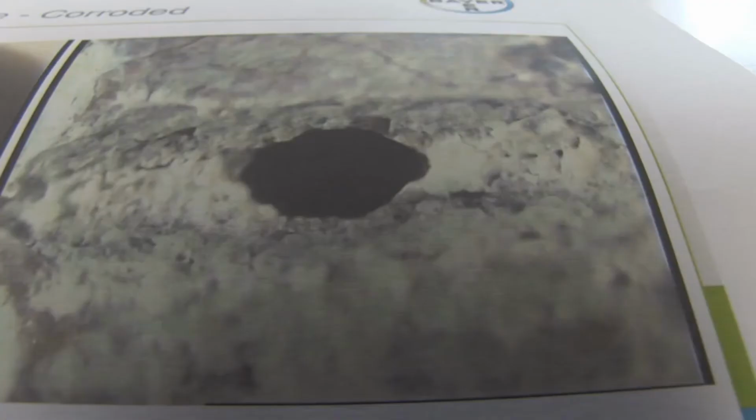I'd suggest brass nozzles, if you're using them quite a lot, have probably got about a 12-month life cycle. So you should consider replacing your nozzles every 12 months if you're using them regularly. They can even corrode. Being brass, they can be susceptible to corrosion, and once they corrode, it can close in the size of the nozzle, again affecting the spray pattern. And once they've corroded, there's no coming back from that. They're basically a throwaway item, and you replace them with a new item.